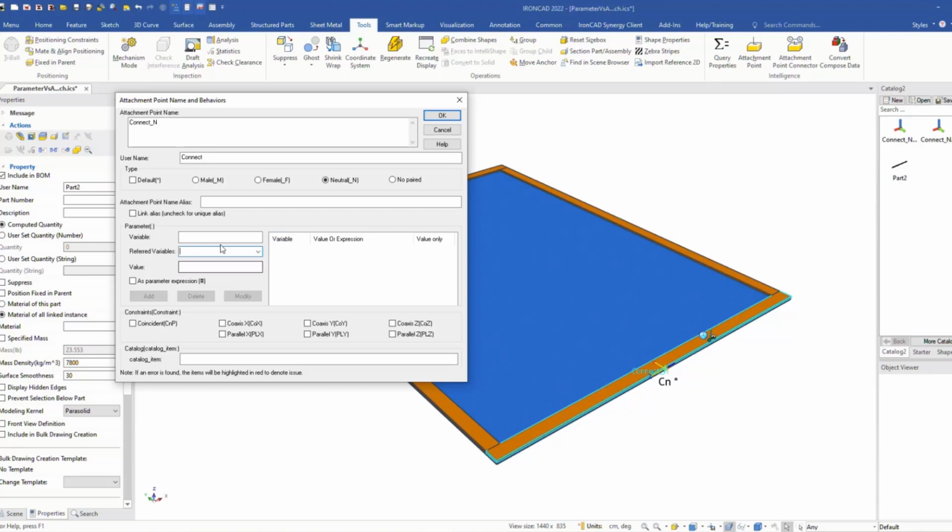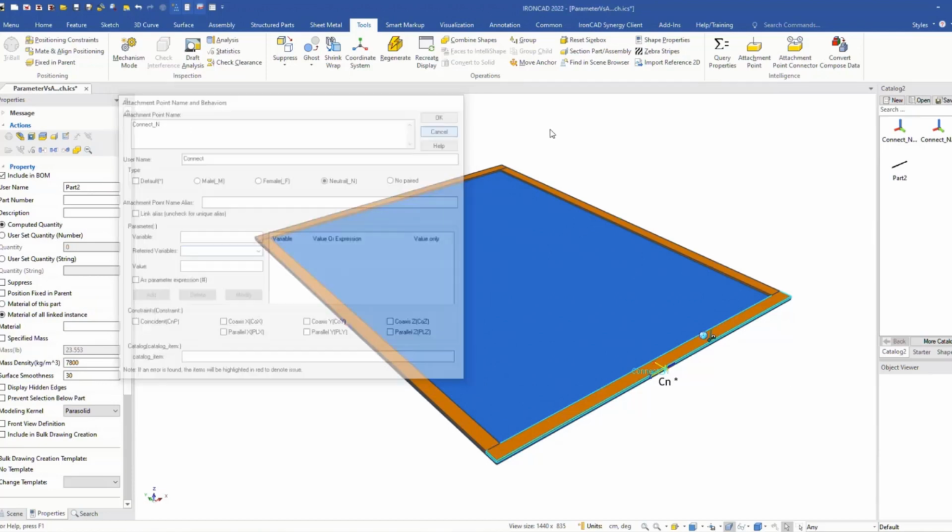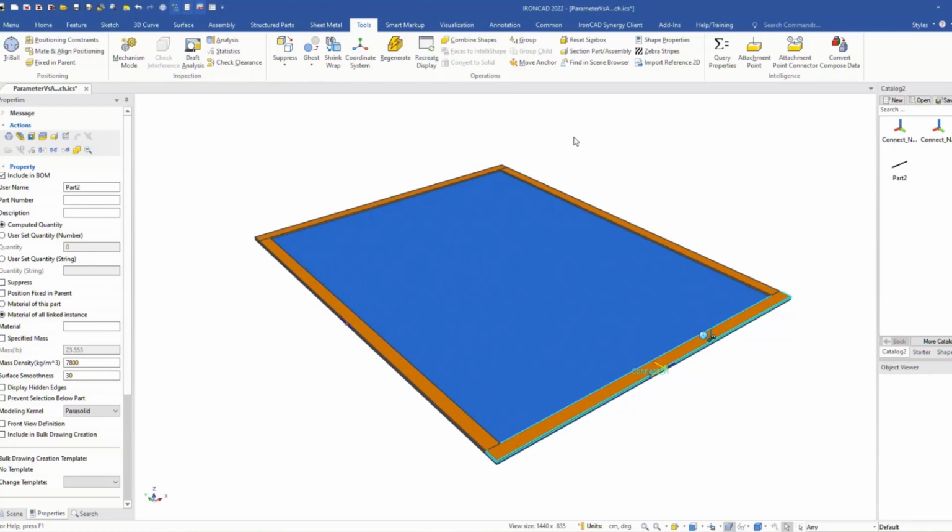So it's a very handy tool that you can build up very long connection strings inside of here with all kinds of information for different parts that are dropping on that, so they could have different behaviors, which is really cool versus doing the mate and lines for various things over and over again. So it can save you a lot of time if you're having multiple or configurable type parts. Hope everyone enjoys this and can make use of this in some of their design process.